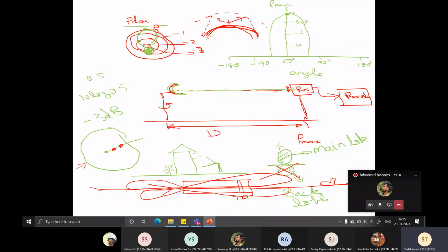Okay. And okay, this is one thing. Now, are you people getting the idea of this radiation pattern? So what they generally do is whenever they design an antenna, they have these field testing stations. Near to Bangalore also they are having one. So they mount this antenna on a pedestal which can be rotated like this, and they will have field monitors. Either you rotate this antenna or you just go around taking all the readings, whichever way is comfortable to you, and then see whether, like your control systems, antenna performance also can be simulated. Okay, so before you make an antenna, you can always simulate the radiation pattern. But after manufacturing, there will be so many issues. So finally you depend on field measurements to see the radiation pattern.